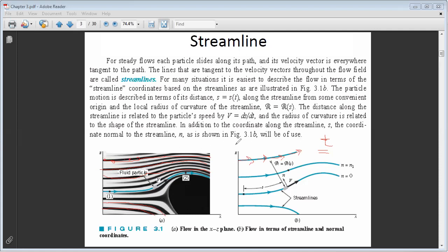This is why, as we will see together after, if I want to get the equation of streamlines, let's say y as a function of x, to plot them, I go back to the definition. What is the definition? At each point of my streamline, the slope is equal to the velocity direction, because we said the streamline can be drawn by just joining velocity vectors. So if at each point I draw the velocity vector, then by joining these points, I can get my streamline.